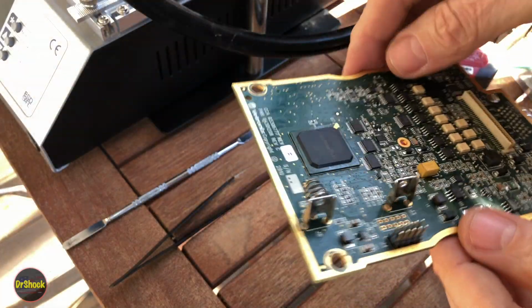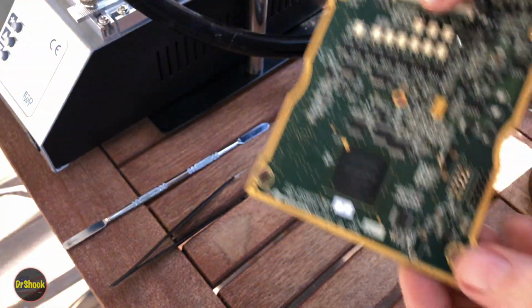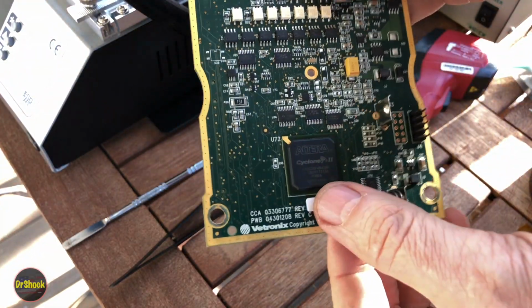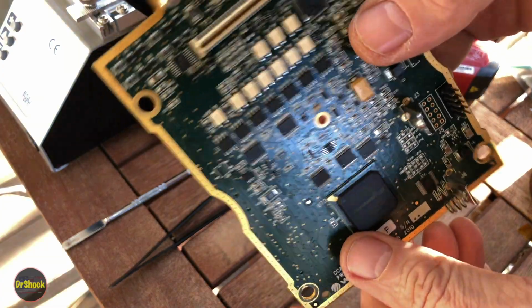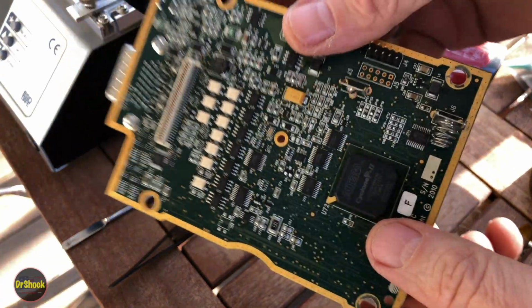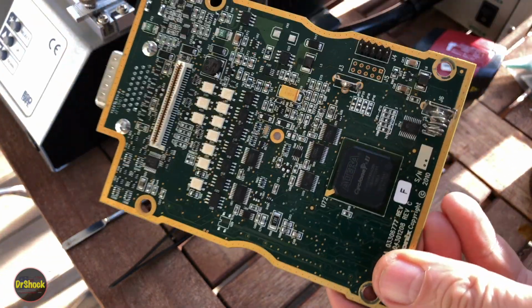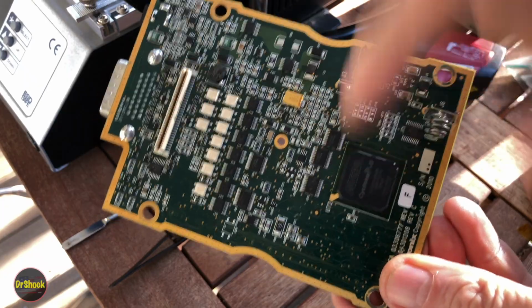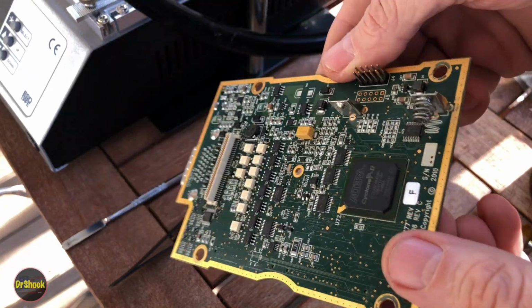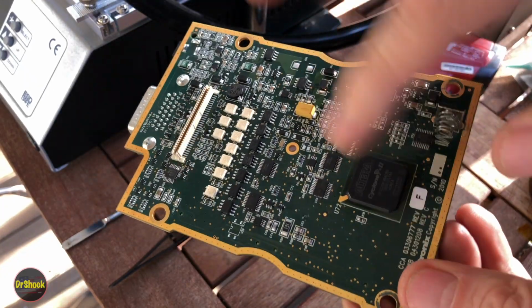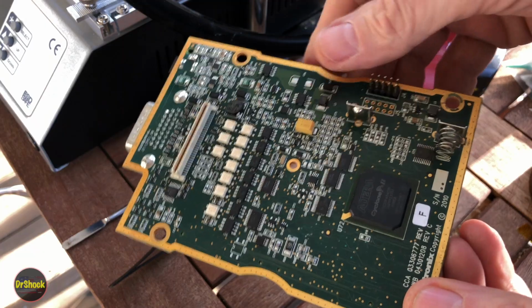All right, guys, next up is this board from the genuine MDI. And again, even though the retail on a used MDI, a genuine, is probably $350, it's still not worth our time to replace this chip. So we're going to try a secondary reflow here as well. Same approach as the other one, although we get a couple of complications.